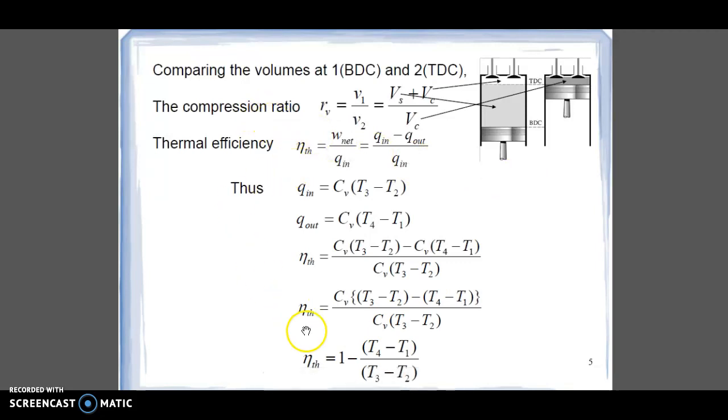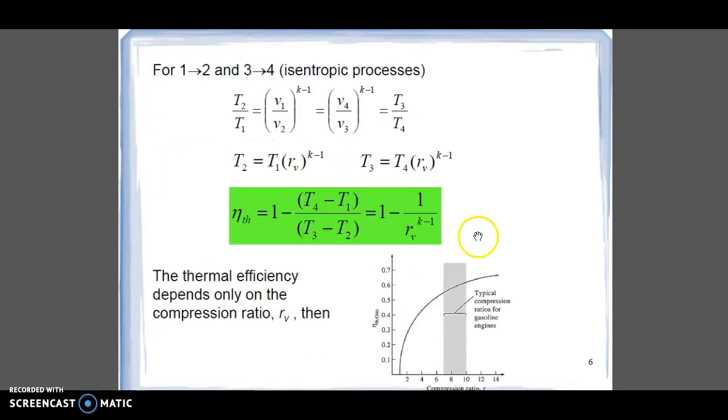So you are going to use the isentropic ideal gas equation. When you have an isentropic process, you are going to make use of this. It's the same as what you learned previously in the Brayton cycle, but the constant in the Brayton cycle is between your temperature and pressure. But for this closed system in an internal combustion engine, your constant is your volume.